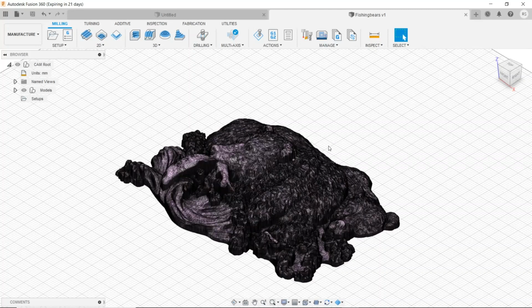So on the first cut, your first cut is always what they call a roughing cut. And the only purpose of your roughing cut is to remove excess material that you're not going to use. It's used strictly for speed, for speeding up the process of cutting this whole job.